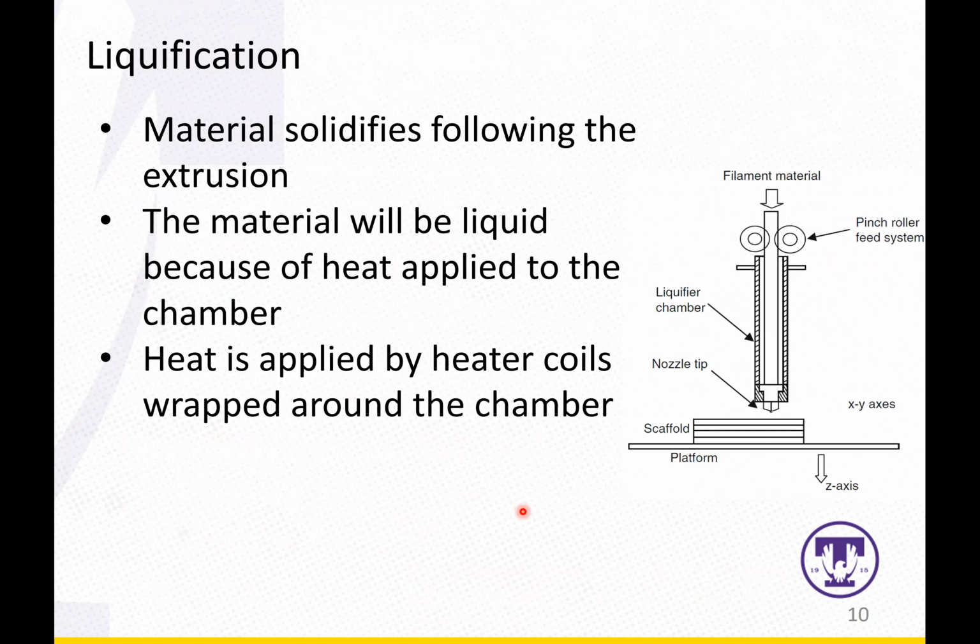And in the liquefaction process, the material solidifies following the extrusion. Here is an illustration of the whole process, how the solid material is liquefied through this liquefier chamber, and then it goes through the nozzle, right? And then the material is extruded onto the platform. The material is liquefied because of the heat applied to the chamber.